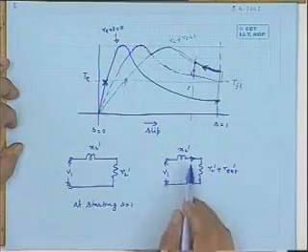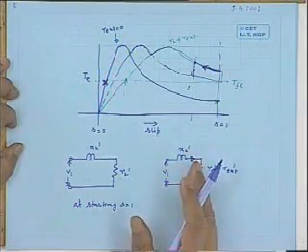It is okay, mathematically we have got all these things. That is okay in terms of this current we are thinking, no? In terms of the equivalent circuit, those equations, all these things. After all, it is a machine, there is a conductor carrying current and it is placed in a magnetic field. BIL something will decide the torque also. Is it not? That you think. I will not tell you the answer today. Because what really has happened, current is decreased, but torque is increased. Why does it so happen? You think about it.